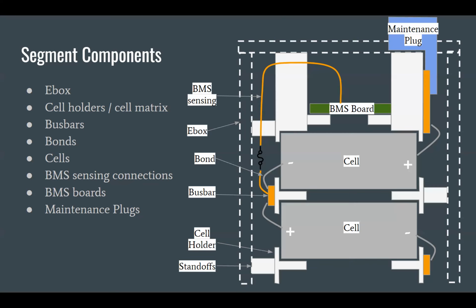And so we just have the practice on the team that if you're ever actually going to be taking this out, here I can use it with my hands, but as soon as I'm taking it out, I can't grab it bare-handed. Mainly because A, from a shock perspective, I don't want to be electrocuted. And B, from a protecting-the-segment perspective, I have oils and things on my hands that, if they get on there, can make it easier for the segments to arc, and they can also corrode the segment.